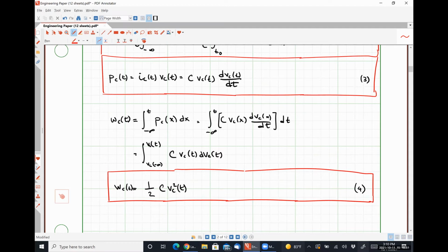But if you understand what this concept of electrical duals means, you really only need to know one set of the equations because you can instantly get the other set by just replacing I and V and changing all your L's to C's or vice versa. They are literally the exact same relationships, 100% of the way. So in truth, you can get by memorizing just 4 and understanding what the concept of an electrical dual means.